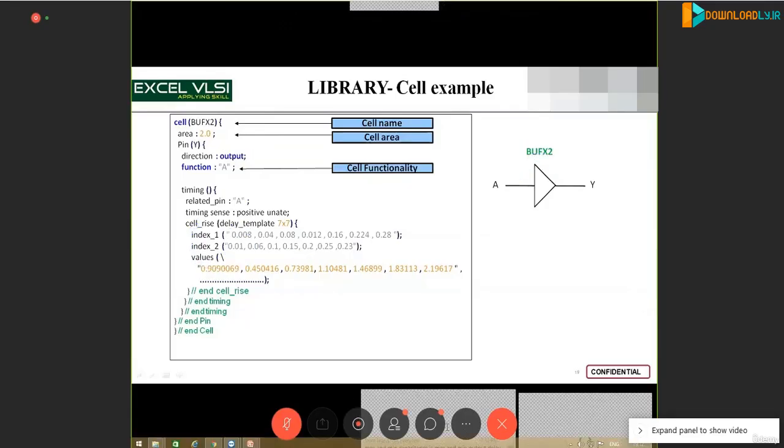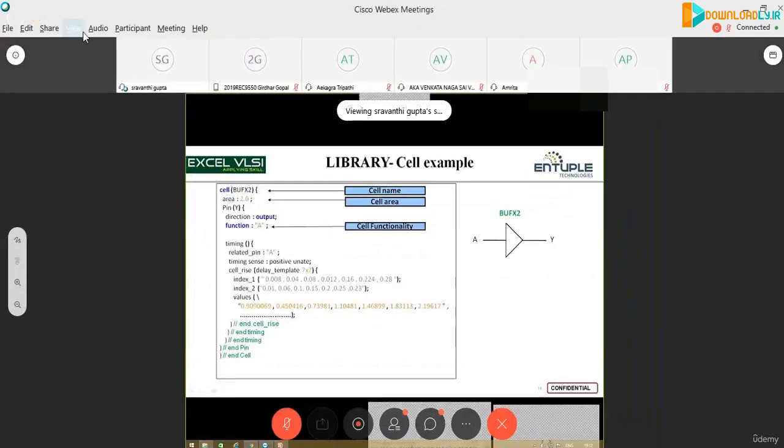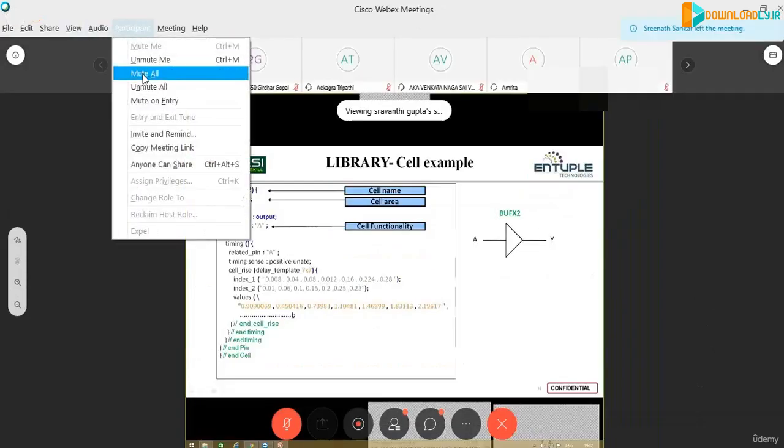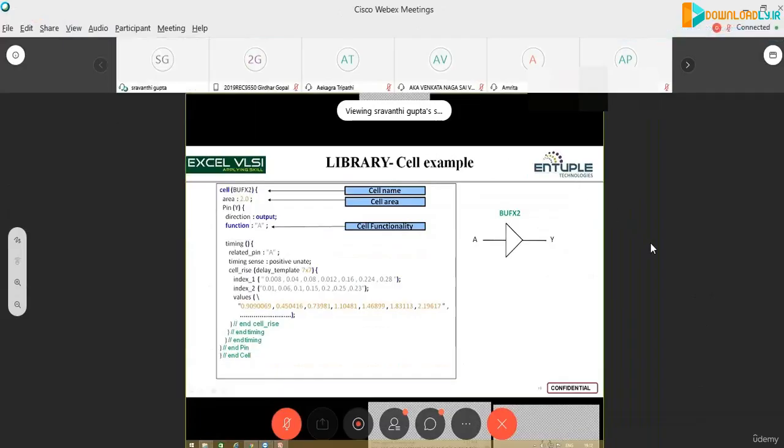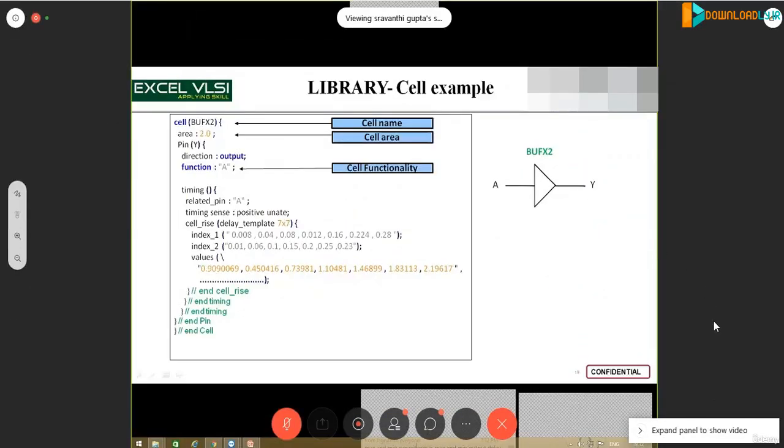So which delay model are we using, and where is it mentioned? That's what I told you. While opening the file and seeing the capacitance modules, you can make out whether it is an NLDM or a CCS model. It is again given by the foundry. That's the reason you need to open the file and see what the capacitance ranges are and so on.